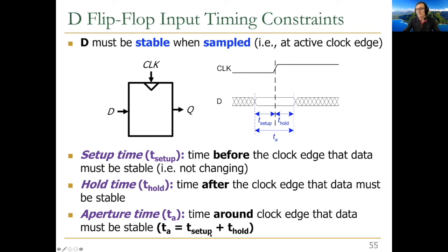So this is very fundamental. This is how a flip-flop operates, and we're going to base every discussion of a sequential system on this assumption. Currently, people try to minimize the hold time as much as possible to 0, but that's not always the case. People play a lot of tricks internally to minimize the hold time, but that's not always the case. So you still need to worry about that if your flip-flops don't have 0 hold time. And almost always, they have non-zero setup time.